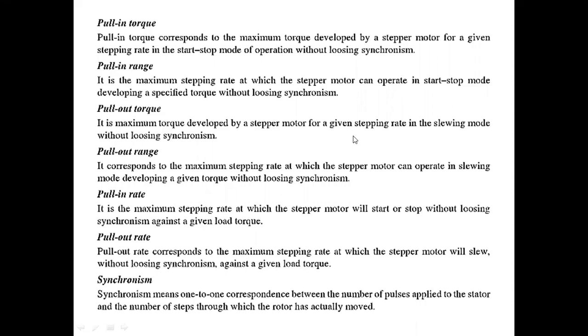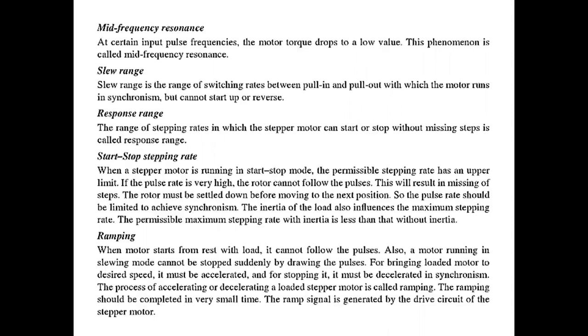Therefore, with respect to the two switches only, the A phase can be excited. Next, we have to change towards the B phase, which is to be excited next onwards. What should happen again and again? Another two switches should be operated. While giving the pulses through the switching circuits, then only the switches can be closed. Okay, that is nothing but the synchronism operation.